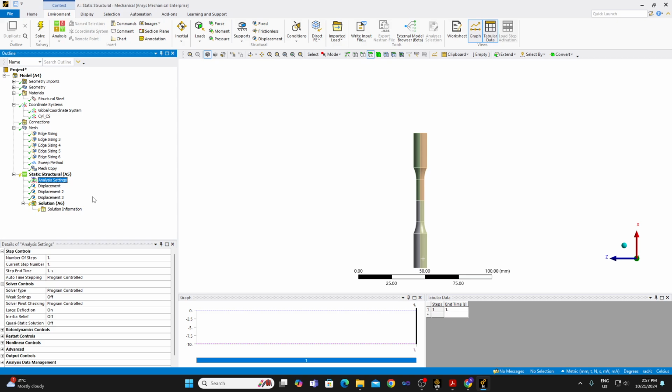because we are looking at applying a rate independent plasticity model. So we are going to be doing a rate independent plasticity model. We are not going to do any viscoplasticity or any rate dependent plasticity, where the strain rate has an effect on the stress value. So in this case, this time is only there as an indication of the load level. So if you apply 10 millimeters of deformation in 1 second, in 1/10 of a second you apply 1 millimeter of deformation. That's what this means.